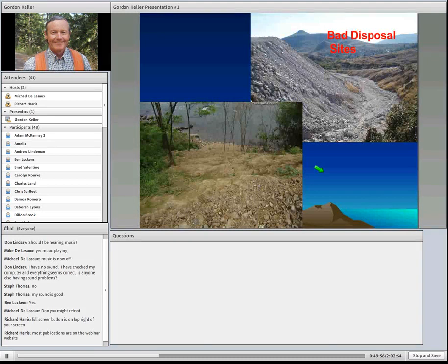I want to mention disposal sites because they're basically just a fill. These are some examples. These are not in California. These are some examples of bad fill disposal because fill slopes, it's predictable. It's going to be about a 1.5 to 1 slope here. And here, if you know where you're starting, 1.5 to 1, you know where it's going to end up here. And if this is choking off a stream, here it's ending up in a river. Those are just places you don't want to be putting fill. And this is a practice I'd seen way back when in the Coast Ranges over maybe Del Norte County, but I think those practices have been much improved now, fortunately.